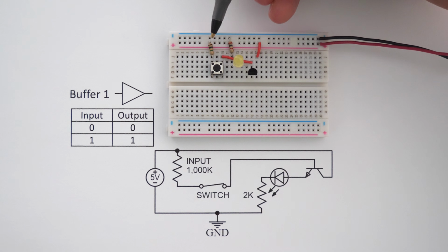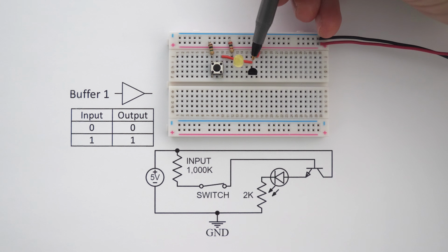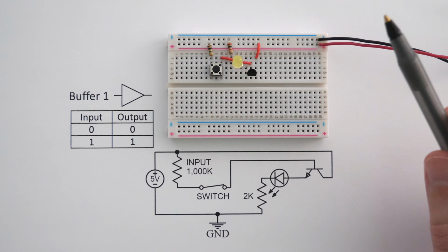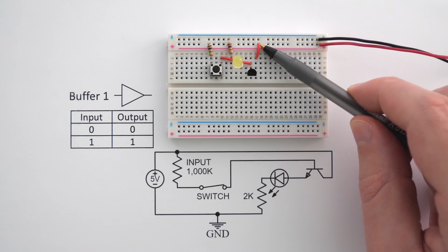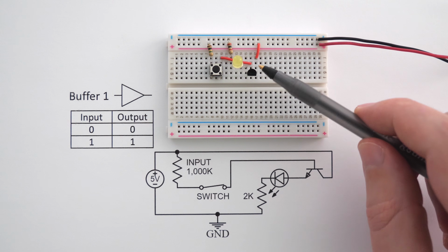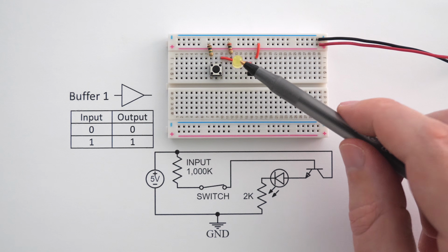So right here we have a 1000K resistor, which is also called a 1 meg resistor, and that is going to be fed across this switch and into the base of this transistor. This is only going to provide 0.005 milliamps of current. However, that current is going to be multiplied by about 100 whenever the current comes from this positive 5 volt rail. So we're going to have current come from this positive 5 volts, go across this transistor, across the